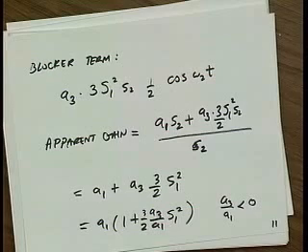So this is not an intermodulation term. This is the term at omega 2, the desired frequency. So the gain of our system is apparently dropped because of this jammer. Well, I guess my question is that basically we're susceptible to everything that's outside of our band. That's true. And that's why it's so difficult to build radios, because you don't have a very well-defined spectrum.